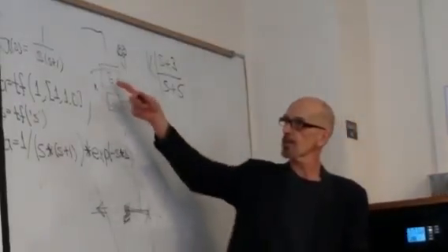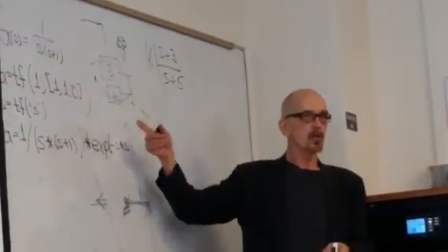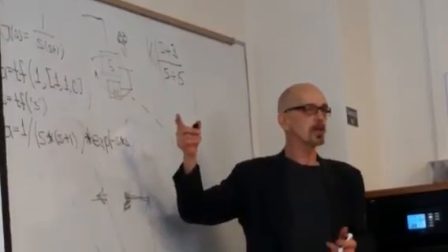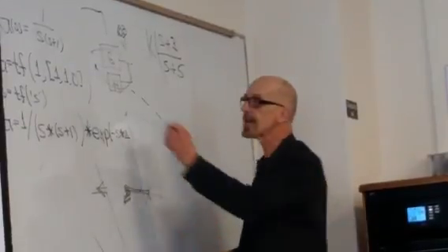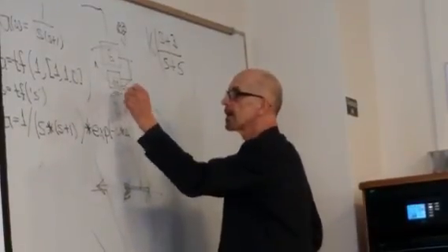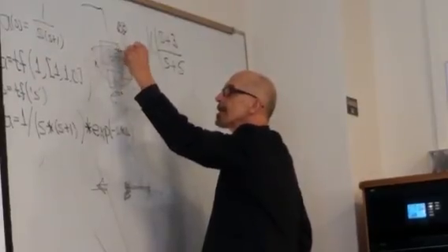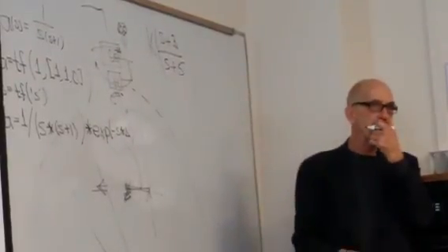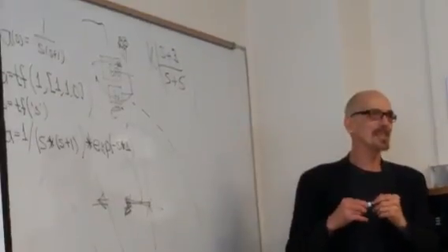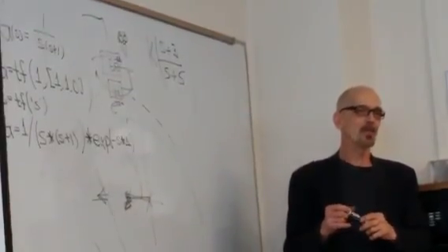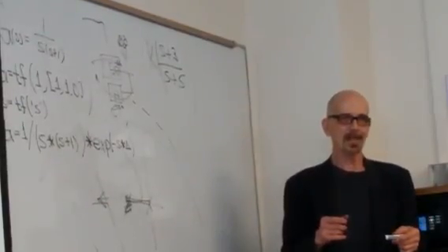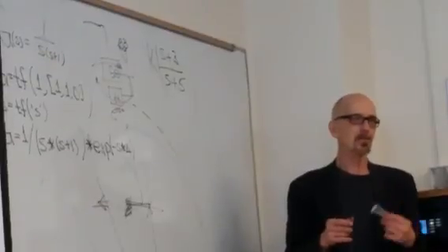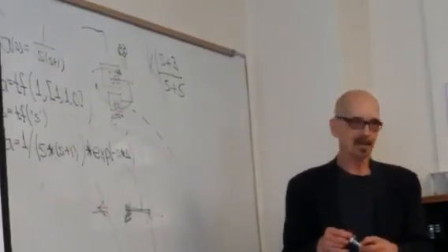So the closed loop for this system is G over 1 plus GH, isn't it? So the crucial element for closed loop stability is not G, it's GH. It's the open loop. And there's an e to the minus s delta in here. So be careful. I'm trying to emphasize it because if you get it wrong in the first part, then it's going to ripple into getting it wrong in the second part, the third part, and then it makes migrating frustrating, and everything gets frustrated. All right.